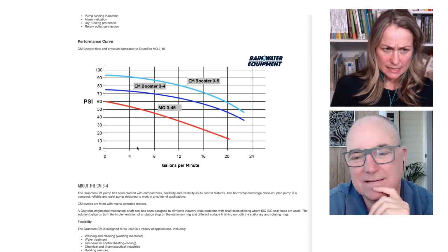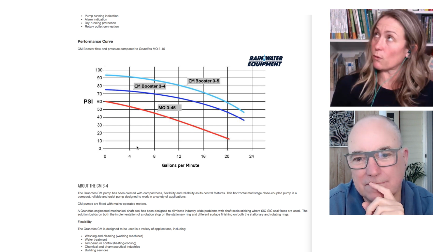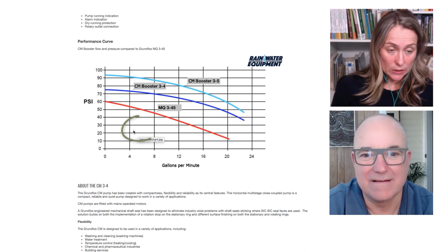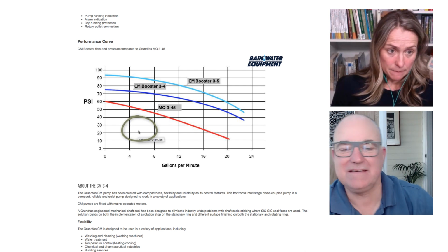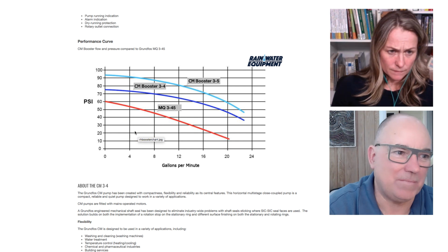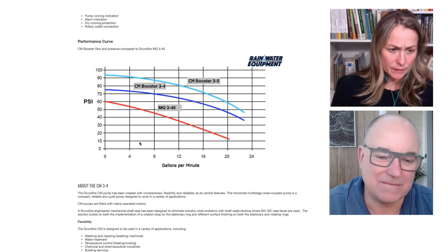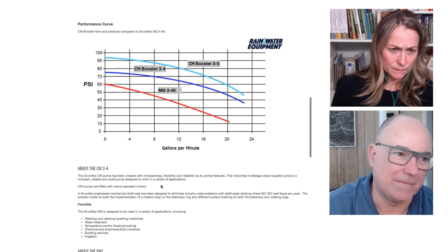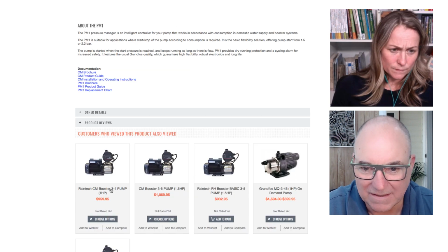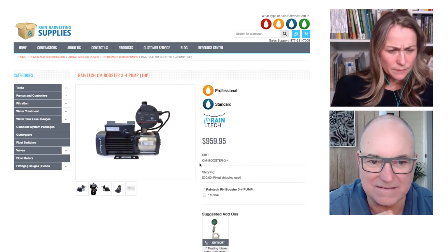And the PSI was like 4 plus 18, 22. So you're right there. Really low. Now this is telling us something very important. This pump is too big for your application. There tends to be an overestimation in the pump market of what sort of pump is needed for rainwater harvesting. These ones are even bigger. So when it's saying 1 horsepower, that's far too big.